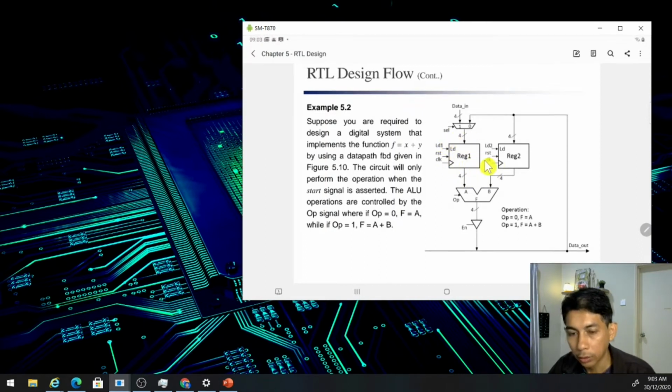So that's why some of you, when you do the Verilog coding and synthesize your design, may get too many warnings. That is because your code sometimes cannot be synthesized to the correct circuit.